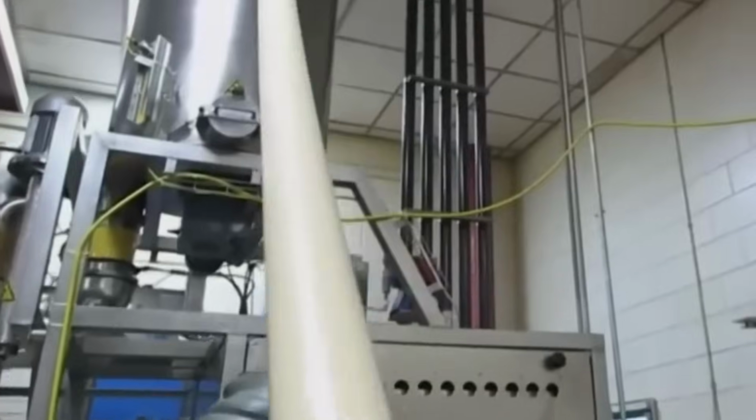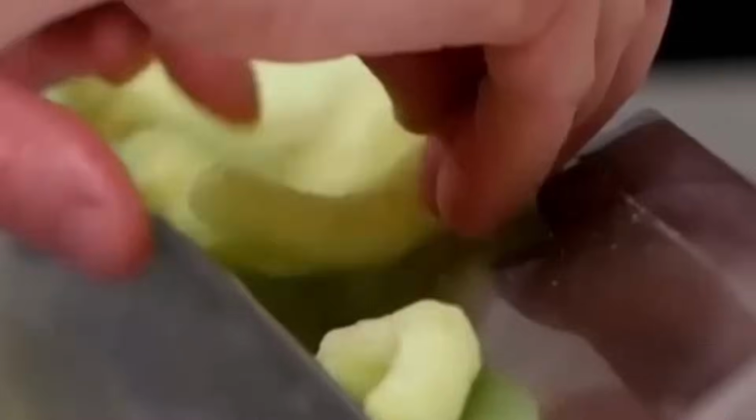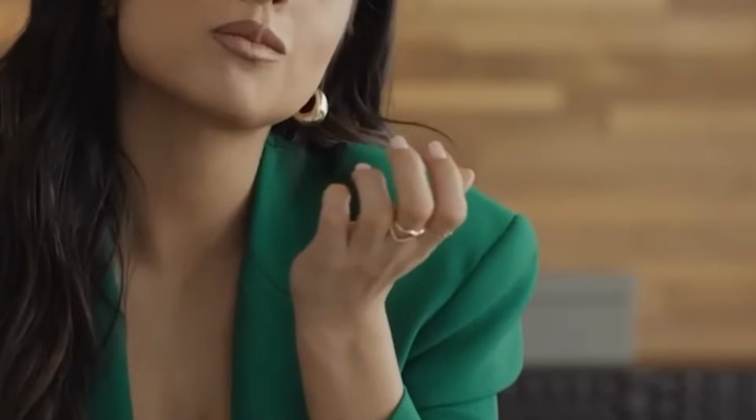For puffed variants, the extrusion process differs at the post-extrusion stage. Instead of frying, the puffed extrudates are conveyed directly into a hot air dryer. The dryer operates at 120 to 160 degrees and includes multiple conveyor decks with perforated trays. Heated air is circulated through the product bed at controlled velocities and relative humidity. Residence time in the dryer ranges from 8 to 12 minutes, depending on piece size and moisture content at exit.